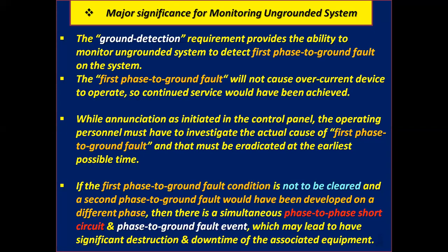Let's start with the major significance of monitoring an ungrounded system. The ground detection requirement provides the ability to monitor an ungrounded system to detect the first phase to ground fault on the system.